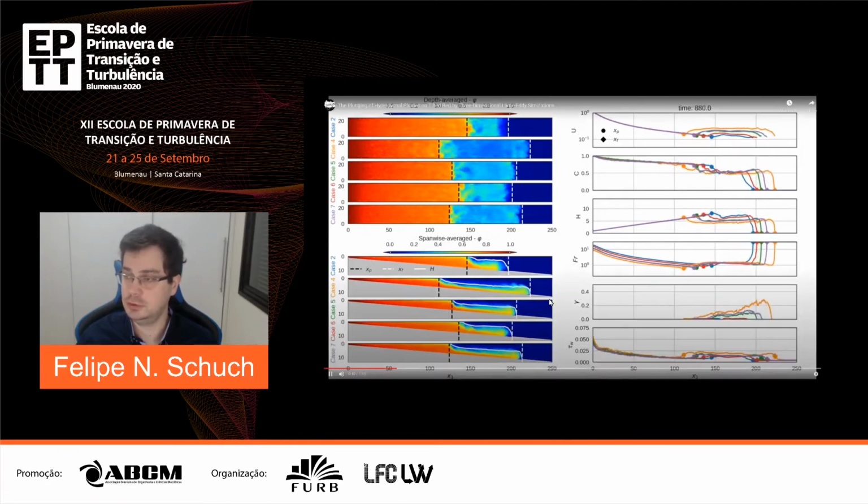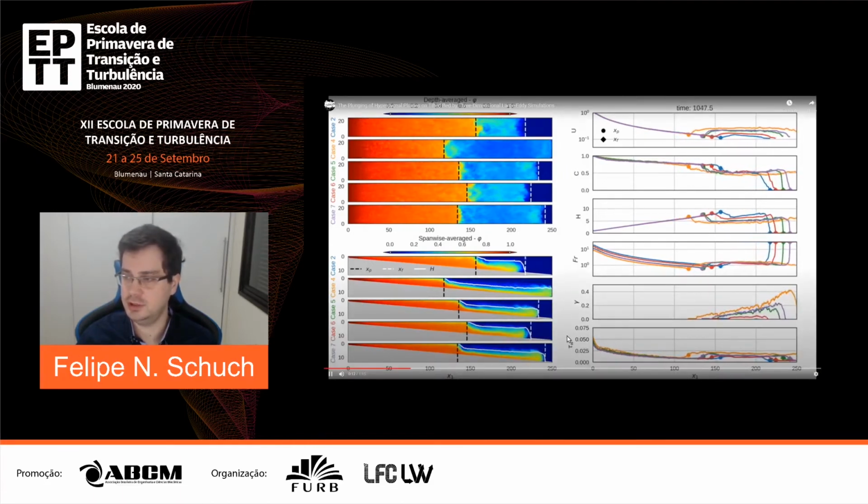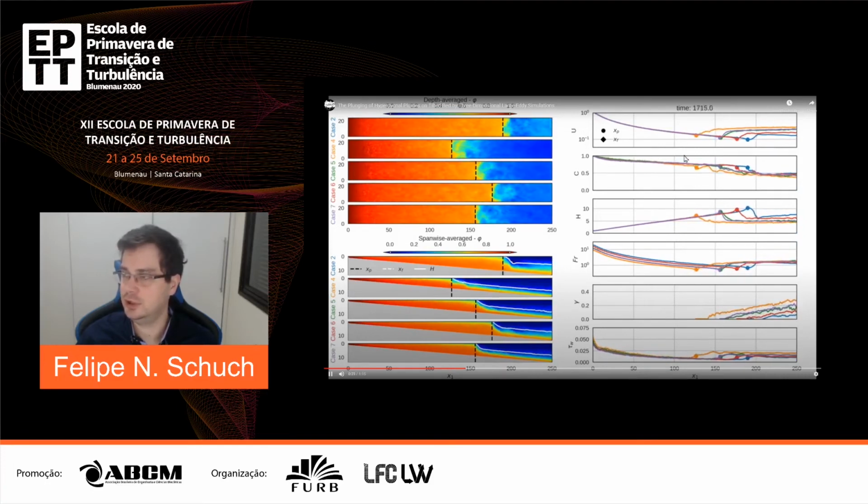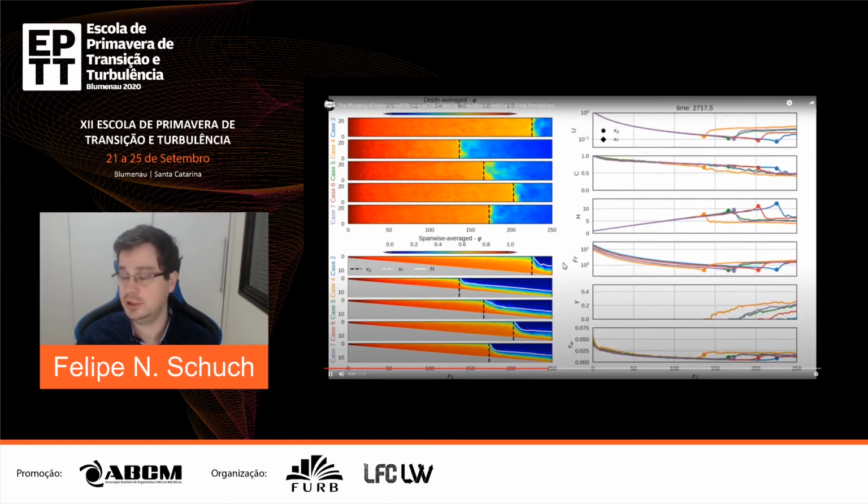Eventually the front will leave the test section for all cases. And we see a lot of turbulence near the inlet as well as in the figures. And an interesting fact: case 2 is leaving the test section. It's critical because the sediment Froude number is very high, so we can't keep the plunge point inside the test section.